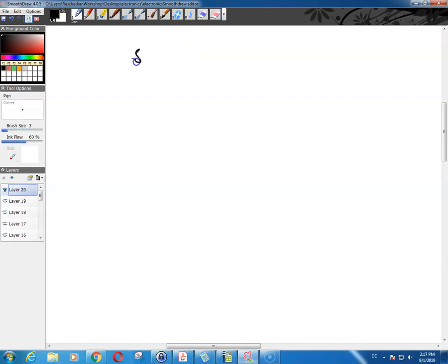I have a single pole double throw switch. So when you say double throw switch, that means that you have a common over here and you have 2 terminals over here, and then the switch can be connected either to this one or to this one. And when you say single pole, that means that there is only one switch over here.